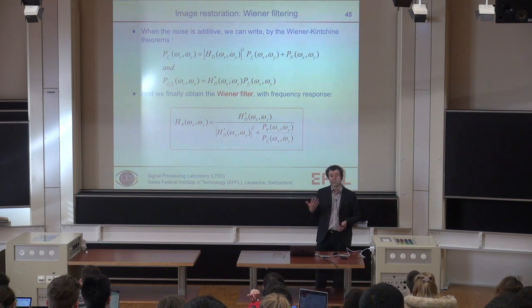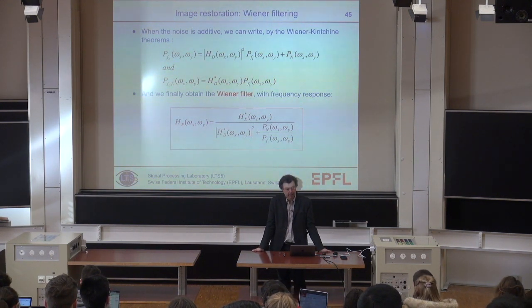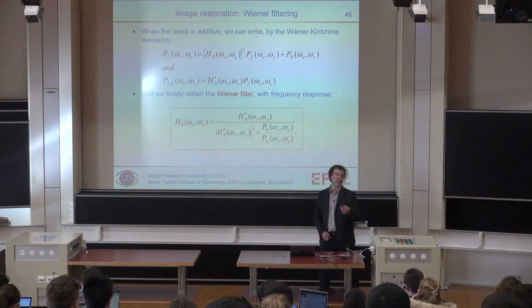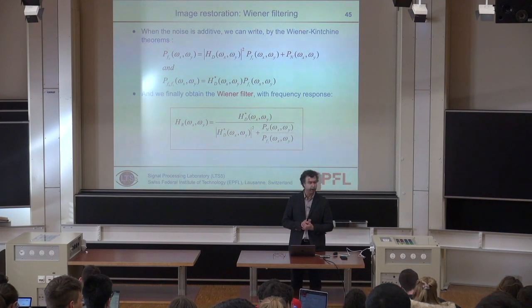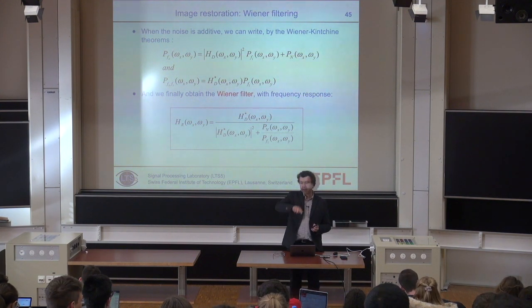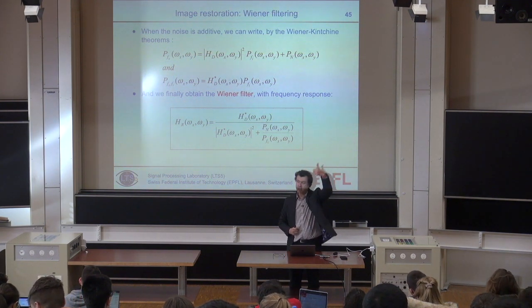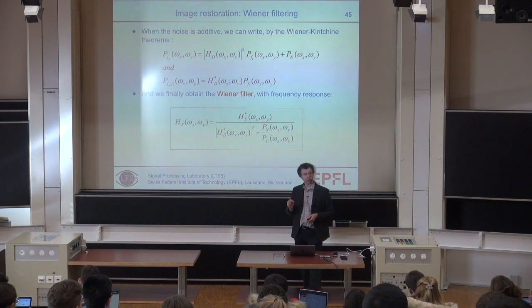Again, same question. You receive an image. How do you estimate whether it is blurred or not? Where do you look to see if it's blurred or not? High frequencies. Where in particular? Let's be practical. Edges. Assume that you know that there is a sharp transition somewhere. It can be a step, so an edge. It can be an impulse. A star in the sky is a very good model for an impulse. And by looking at that, you can estimate if your image is blurred or not.